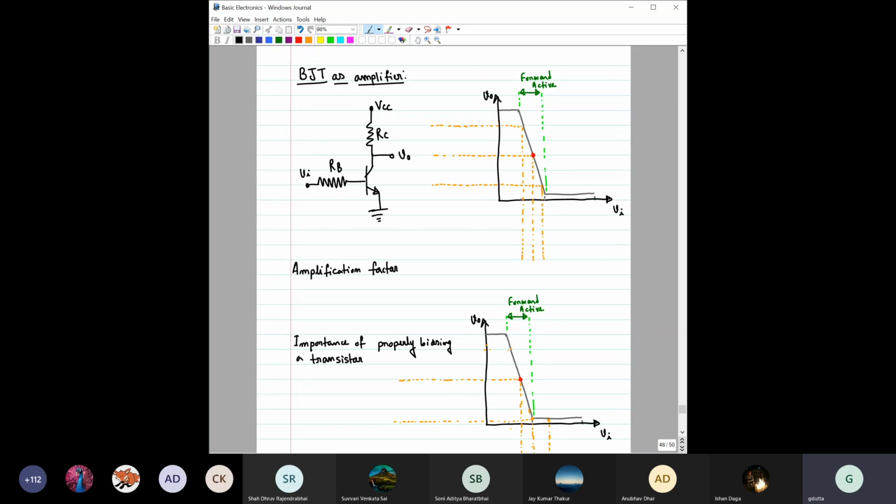So obviously at this input we need an AC signal. Say this is that AC signal, V source. But if we suppose we make it ground here, will this work? This will not work, because this source signal will be so small that it would not be able to make this PN junction forward biased. So we have to apply additional DC voltage to make sure that this junction is forward biased, and that is what biasing means.